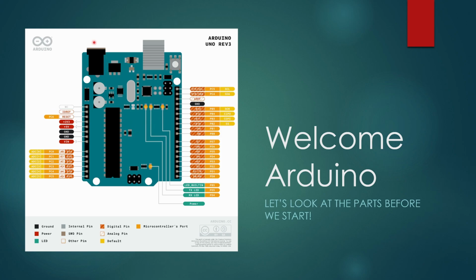For example, there's a power supply that converts a broad power supply with special circuitry to a certain power that the Arduino can take. There's a crystal on here that acts as a clock signal for the microprocessor. There is a chip on here that handles the communication with the computer. There's USB. If you want to program the Arduino, you use USB, and this chip does the communication with the Arduino and tells it, hey, this is the program that shall be put onto the chip. You can also talk through this chip with your application that's running on the Arduino while the microcontroller is running. So if this chip is not programming, it can still talk to the microcontroller and tell it what to do.